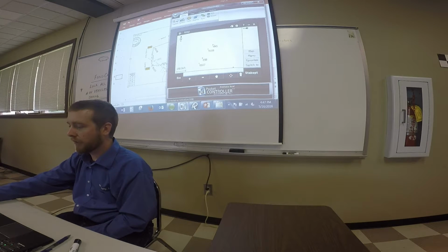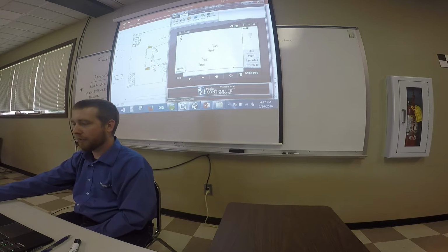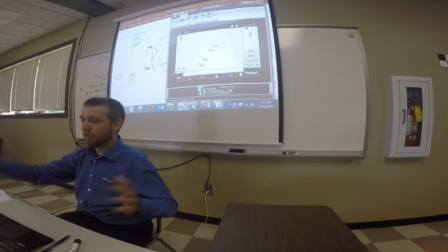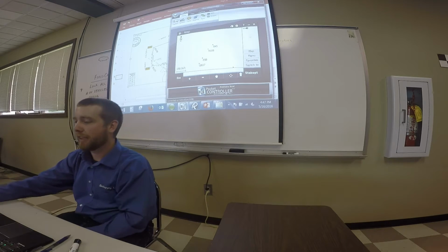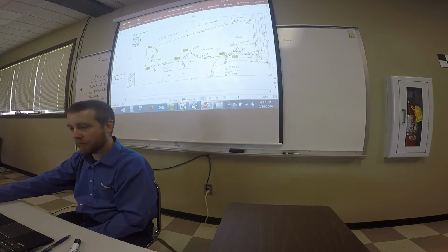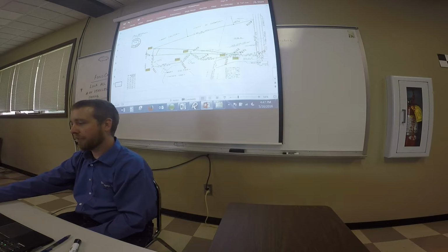Okay, so there's 845 up here. Well, there's 9108. It's way off, away from where it should be. Here's 858, here's 9107. The whole thing needs to be rotated. Okay? So here's what we're looking at right now. 9101 and 103 are the same point, but 9108's way down here from where it should be, and 845's up here. So now we need to know what this angle is that we have to rotate to.